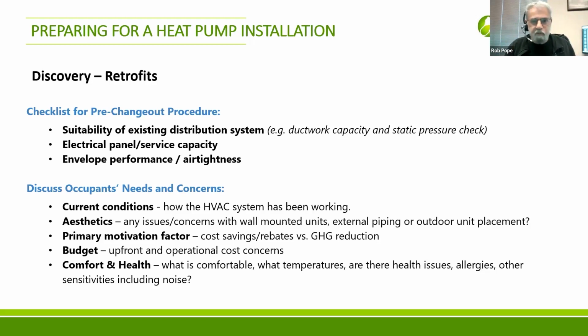You're going to tighten up, weather strip here and there, blow some more insulation into the attic, maybe change the windows. Those things have to be considered in concert with your HVAC system replacement. You've got to take into consideration how the building's going to change so you can properly size the equipment.